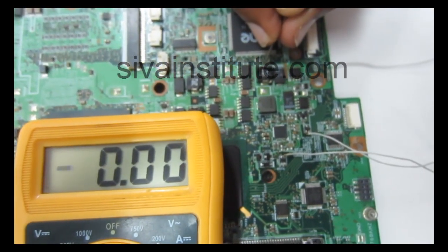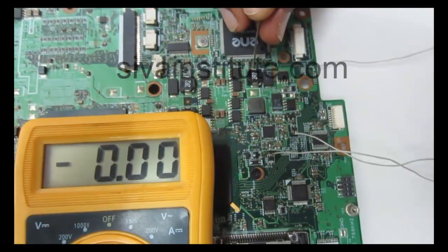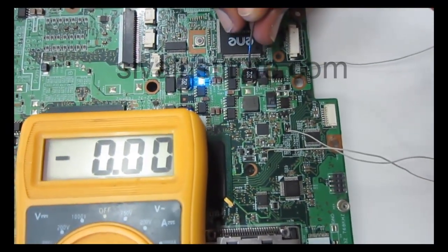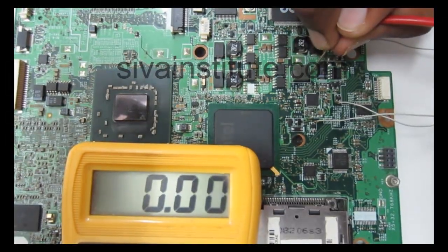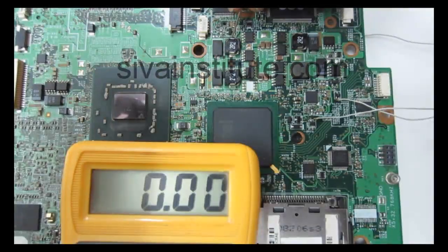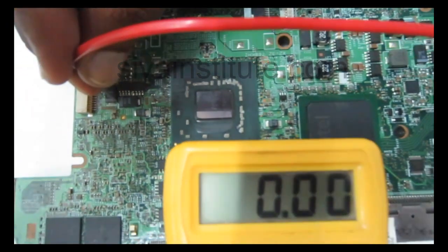Now I disconnected S5. Now I will connect the S5 connection. This voltage will come after the S5 command. I will give the S5 command. See here, 3.3 volts is okay. No 5 volts, but in some sets this voltage will come. No voltage at this point. That is memory supply. No voltage at this point, and this voltage also. No voltage at this point.